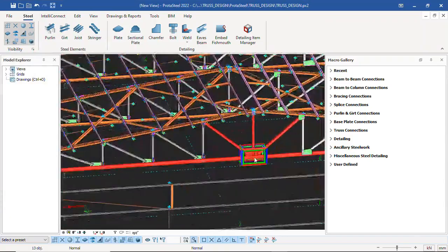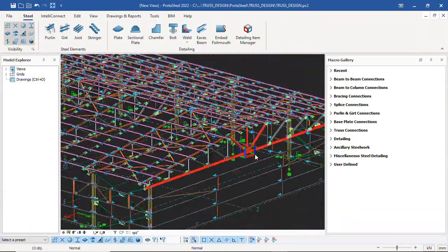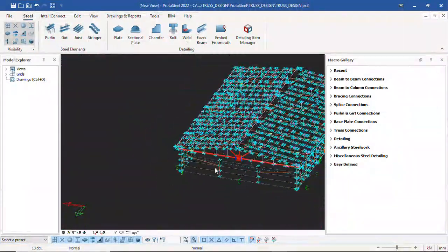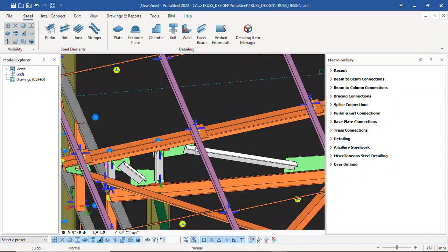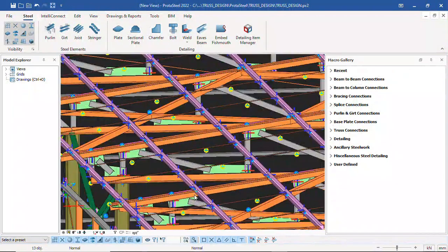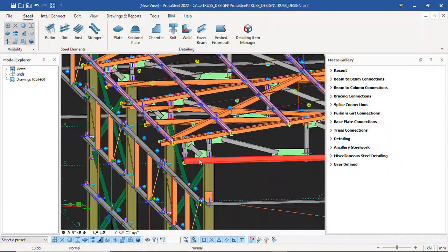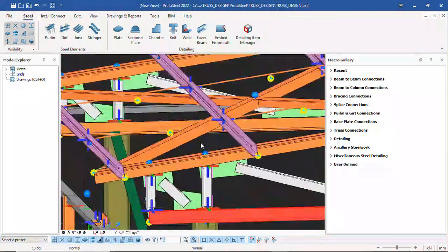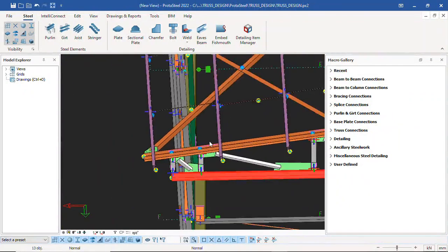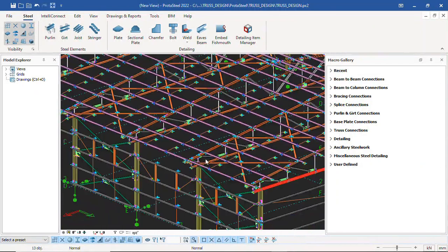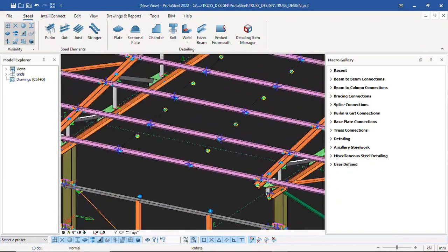So now when you go to our detailing, I can show you how you can get your detail view. You can have as many detail views as possible. Any places that you see that it is not too clear, where you need to show clarification on how the connection is done, you can have that box. So when you go to your detailing, you can click on it and have a detailed view of that. The essence of your detailing is for your drawing to be simplified. Okay.